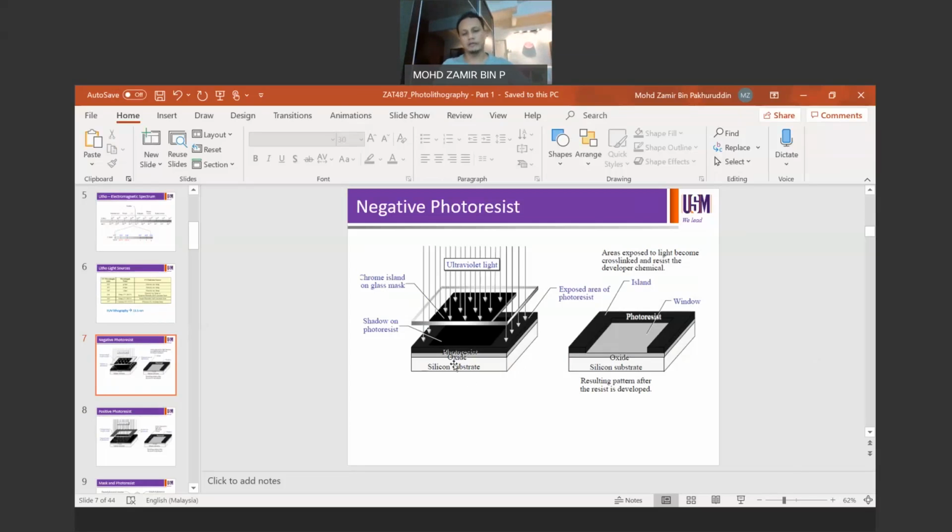So just imagine that if you have a DUV system, so your UV light here has an illumination wavelength of 248 nano, and then you have your reticle here that we've seen on our earlier pages, the mask that you have to use in order to define your patterns. So this reticle actually allows a transmission of the UV light through some regions of its surface, and it will also block transmission of the light on some other areas.